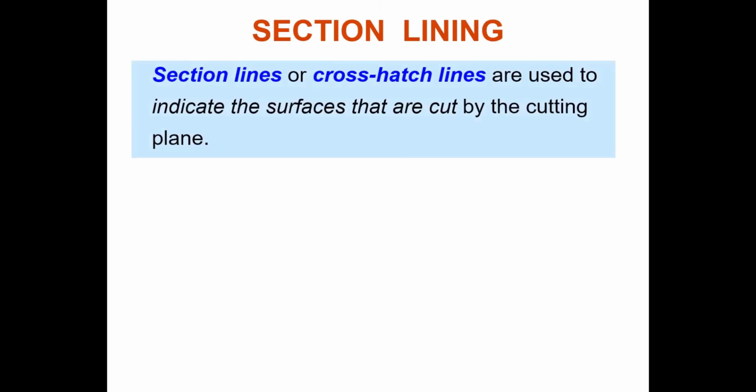To me, if you use the middle grade, it overlaps, because your center line and hidden line are HB, right? If you do the section line, it's also HB, so it overlaps with your hidden and center lines. Make it 4H. Clear, class? By 4H. Lighter. Understand?